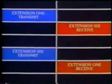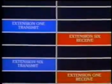Through intermittent transmission on two address buses, these commands are made available to the system, each in its own turn. This sequential commanding allows voice information to be transmitted and received at the proper extensions. Now, the ROLM CBX divides time into frame periods, which are 83 microseconds in length.